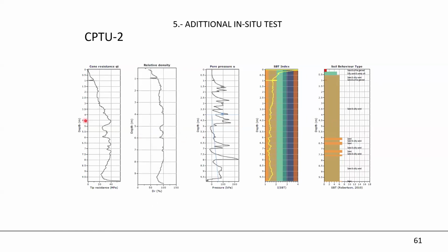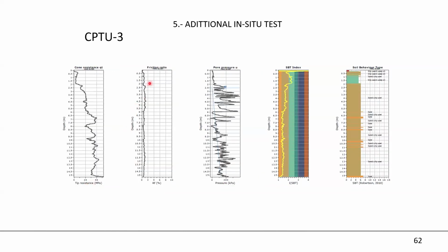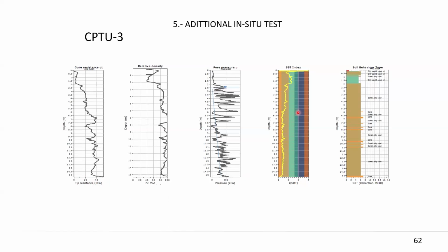And if you don't know some things about the CPT, that is the correlation for relative density. And the relative density is very near to 100. It's really compact sand there. And we touch the sandstone near 10 meters. Okay. And in the other CPT test, we have very similar results. We touch the sandstones at like 15 meters, and the relative density is more than 90.